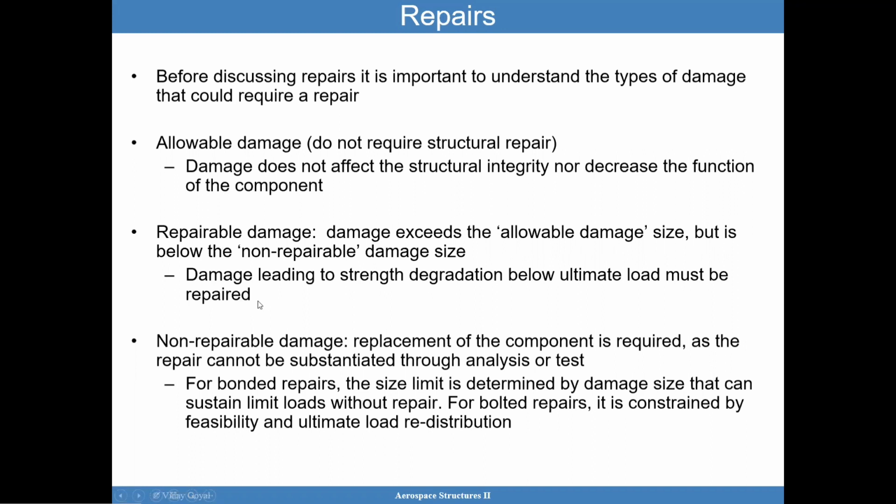A repairable damage is one where the damage exceeds the allowable damage size, but is below the non-repairable damage size. And so the damage leading to strength degradation below ultimate load must be repaired. Non-repairable damage is one where the replacement of the component is required because the damage cannot be substantiated in any way. And so in those cases, you have to replace the component.